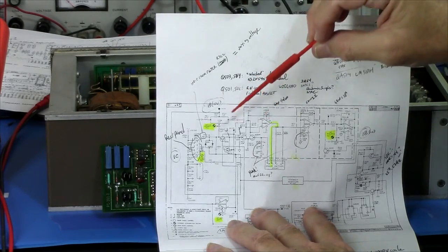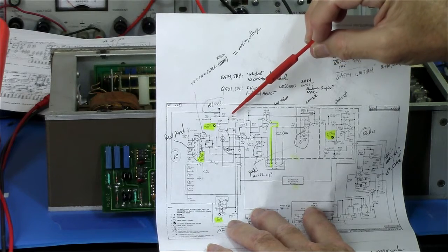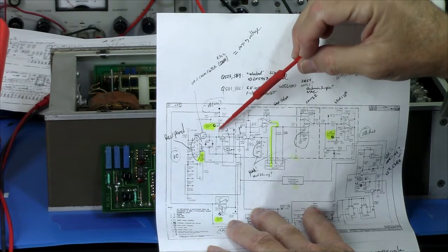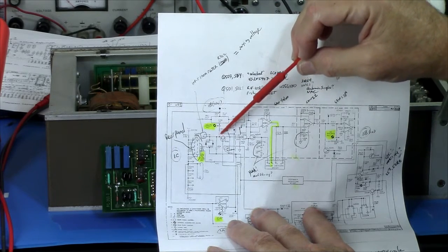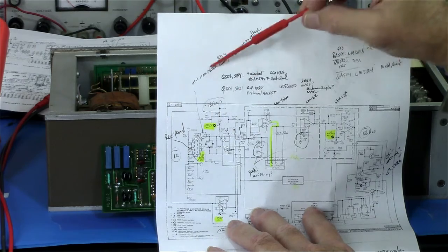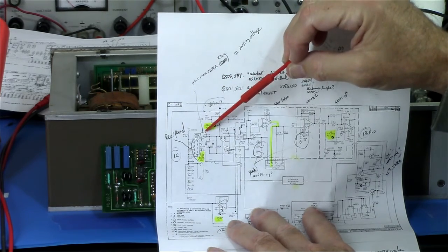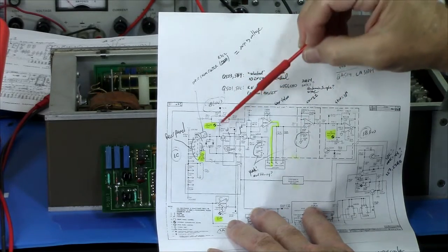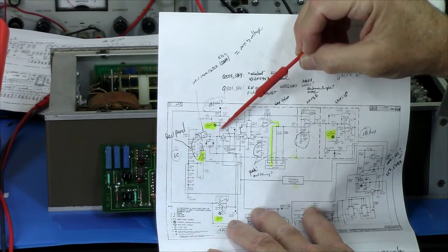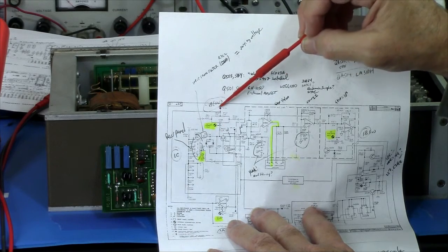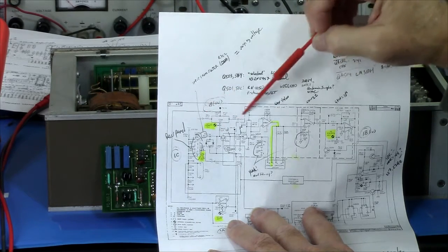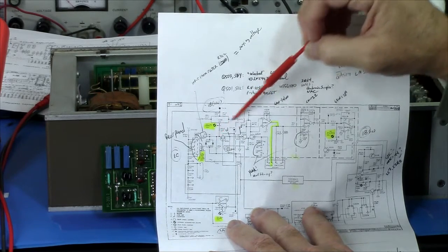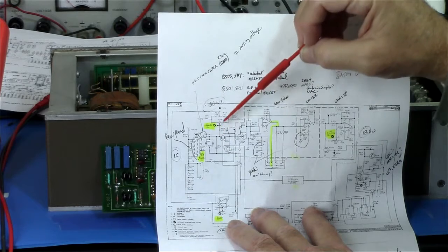Okay. What I'm seeing is voltage here at this node. Now, if I pull this card out and measure that on the back plane, it's 0. So it's coming from this card. Okay. This is the resistor I've lifted. So you can see here there's plus and minus 15. Okay, and it would come down here. So that could affect this point.